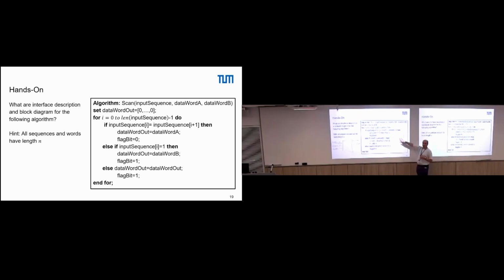So, this is just a register, right? It just stores, and then every clock cycle it updates. We will look into how this works internally later in the lecture, but for the moment it's sufficient that it stores, and in the next clock cycle it updates. This comparator here, we will also have a quick look at somewhere in the lecture, just compares: is the data word I receive here the same as the one I receive here? So this is the previous clock cycle, let's say I. Then whatever goes in here is I plus 1. So we have the comparison of these two.